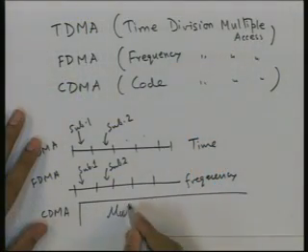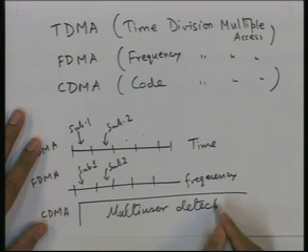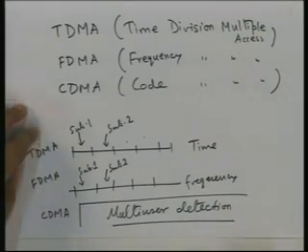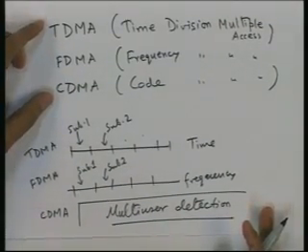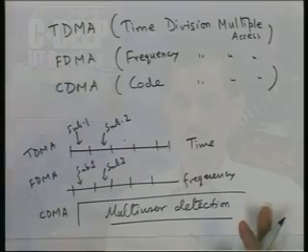Okay, now the base station of course has to know how to detect the different symbols. There are different ways of detecting, because he is receiving the sum of all the signals that are being transmitted by different subscribers. So he has to now separate the signals, separate the information that is coming in different signature sequences. He is not receiving them separately. They are getting added in the channel, and he is receiving only the sum. So now the base station has to separate the information from the received signal, and that is again an area by itself. It's called multi-user detection. Again, multi-user detection is usually studied in a separate course on wireless communication, and networking is usually studied in another separate course altogether.